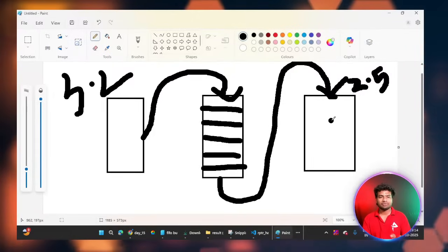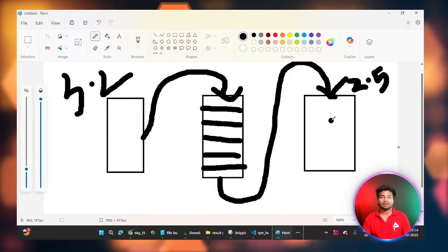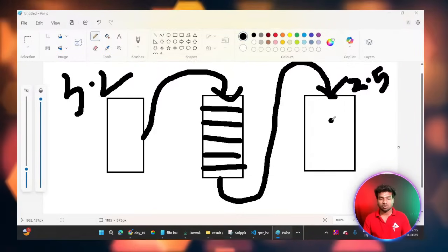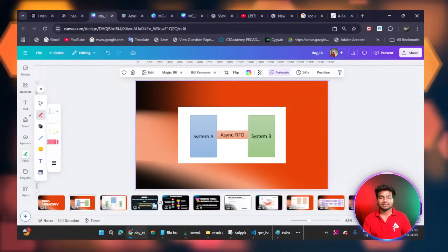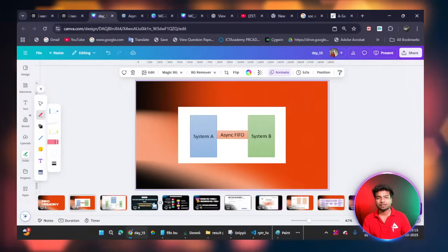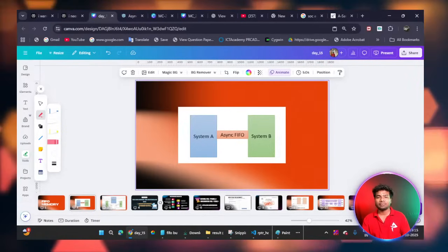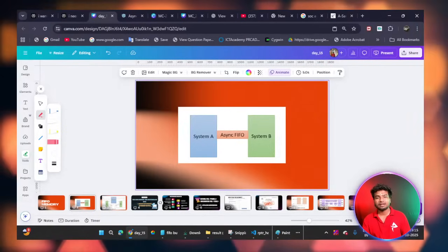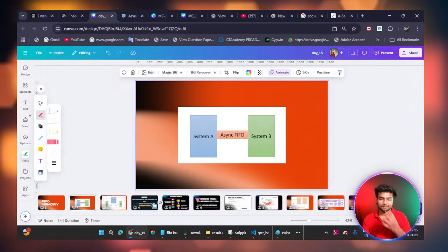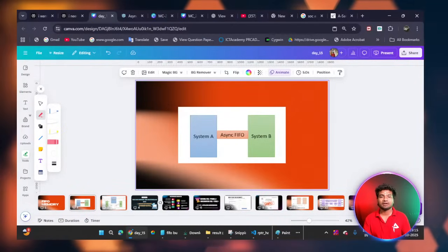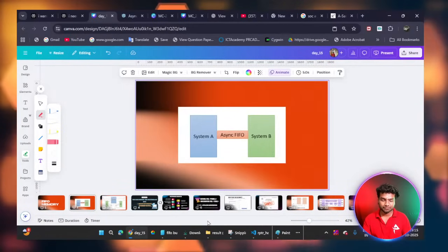This is how the FIFO works, and there are a lot of techniques in clock domain crossing. The main definition of clock domain crossing is, there are a lot of different clock domain blocks in our chip, so we need to make synchronization. We can use techniques like the FIFO technique, the pulse synchronizer, and a lot of other synchronizer techniques. You can use anything. The basic and simple synchronizer is the FIFO buffer synchronizer. By using FIFO, you can make synchronization.